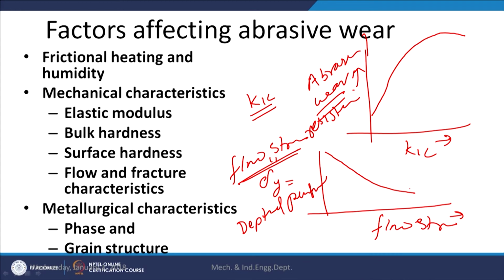So, which will be responsible for determining the depth of penetration by abrasives. If the flow stress of the material is increased, then of course it will reduce the abrasive wear, certainly up to some extent. But a significant increase in the flow stress means the material will tend to behave like a brittle material also.